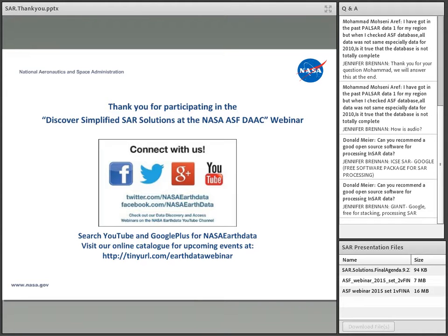The next question is, what do you offer for L-band atmospheric correction, both for ionospheric and tropospheric correction? Is a package available for ISCE or ROI_PAC for this aim? You have some publications regarding this topic. Would you please guide us briefly?